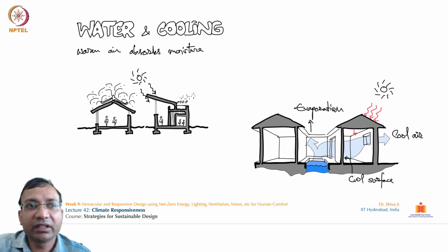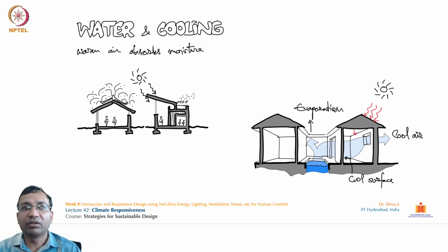Similarly, for the shading and cooling effect, how these pergolas and other sunshade devices can be installed in which parts of these buildings, and how this can be maximized for efficiency. You can see here this double roofing treatment is given, to minimize the overall heating in the bottom floor. So there is a buffer area of air only, because air is one of the best materials for thermal insulation. This air is also naturally trapped over here, creating a buffer zone.